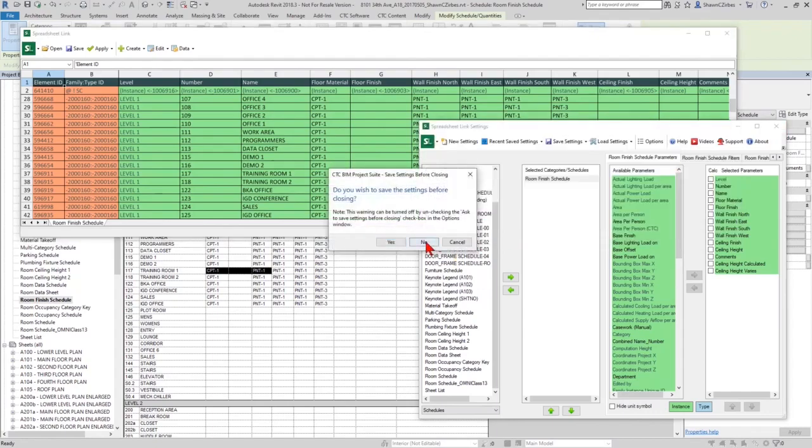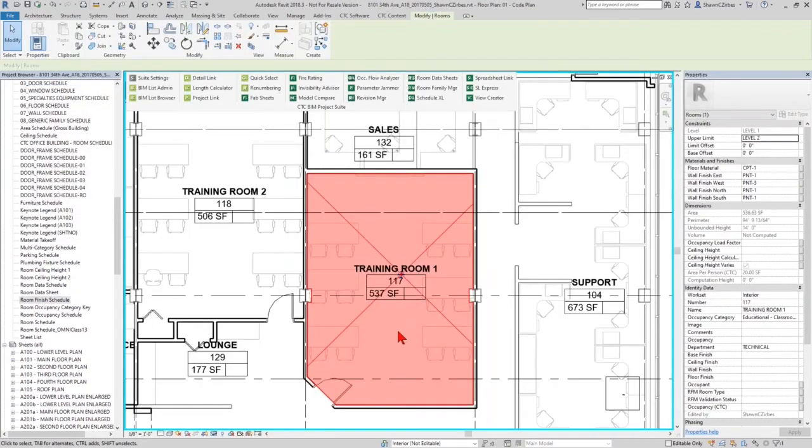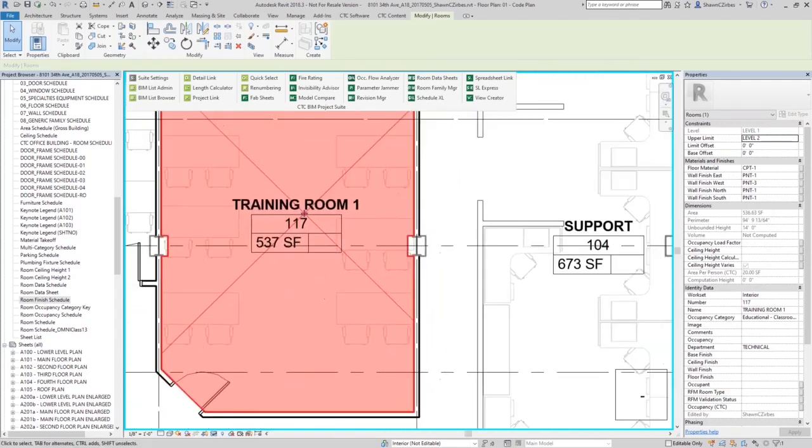But here's where the Spreadsheet Link becomes really powerful. Let's talk about things Revit doesn't do super well. If I click a room and I have an occupancy parameter down here, I want to fill this occupancy parameter on this system family. Room is a system family, means you can't edit it outside of Revit. You can't write your own formulas on it outside of Revit, element by element. I want to simply take my area, whatever my units of measure are, and divide it by some load factor.